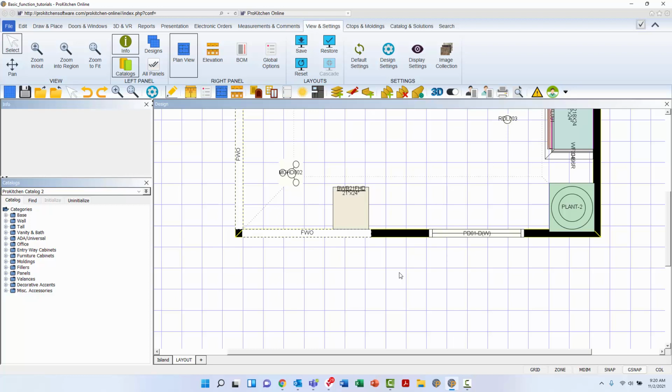of the new setting. When you need to select a countertop texture that differs from the default settings texture for a single design alone, you will need to do so in the design settings. Design settings are generally one of the first things you will do upon creating a new design, as this is where you will name the design, provide the customer's information, set design-specific construction and texture parameters, and enable your one-click Add All Molding and Molding Lighting.